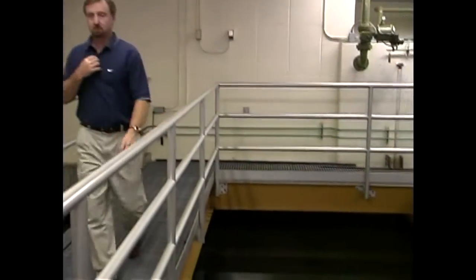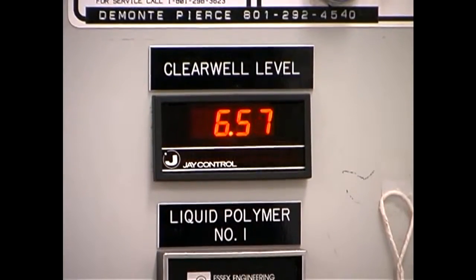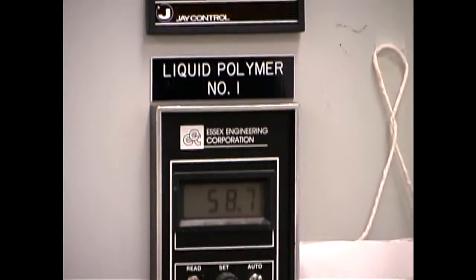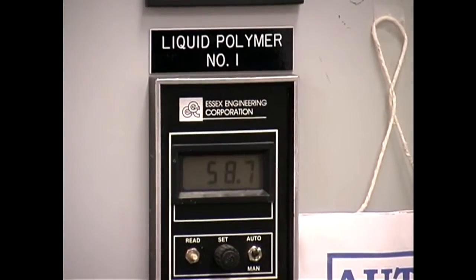Right now, like I say, we are testing a polyaluminum hydroxide. We're not sure if that's the polymer of choice or the coagulant of choice. Right now we want to be able to feed a little bit of ferric to get rid of the arsenic, but we want to get that into some level that's more controllable for pH. But I would imagine that that's probably where we'll be 6 months from now.